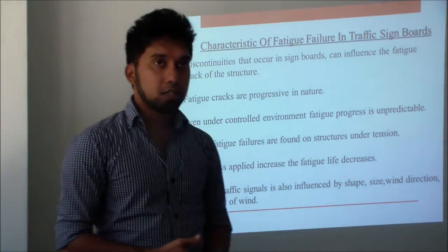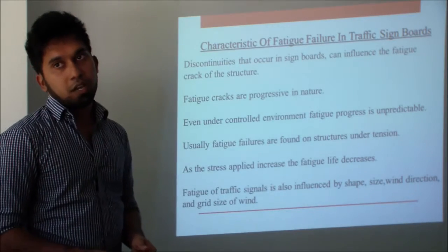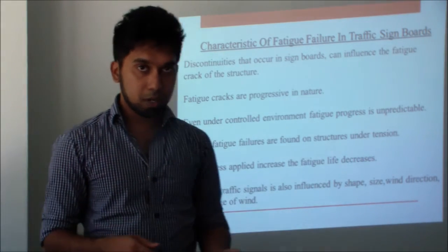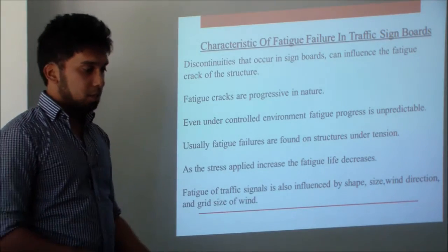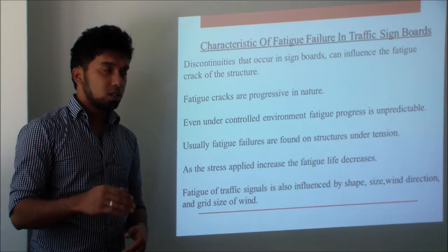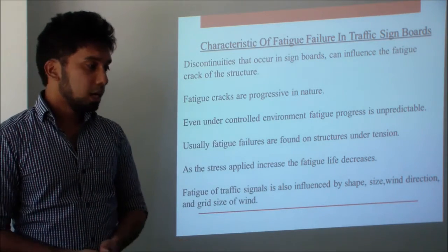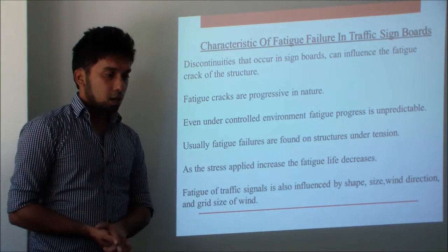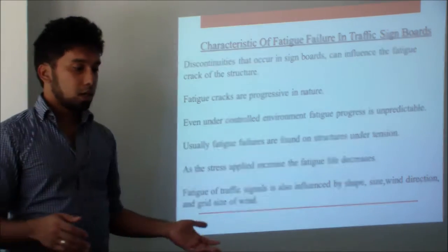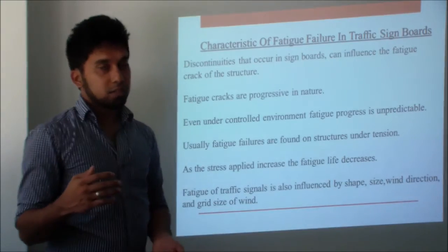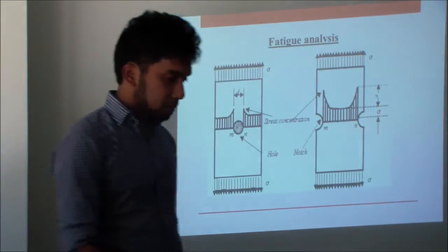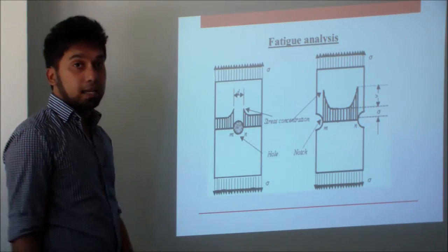Usually fatigue failures are found in tension members. Fatigue failures are also found in compression members, but it's usual in tension members. As the stress applied increases, fatigue life decreases. Fatigue of traffic signals is influenced by shape, size, wind direction, grid size of wind, etc., as I already explained. Now moving on to the analysis.